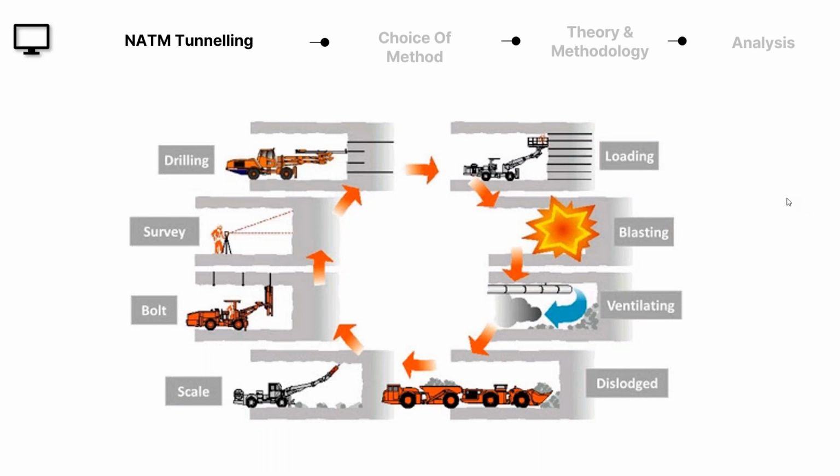The entire chain of process starts with a survey, where we have to drill and what kind of material is present. Post survey, the holes are marked. Then we go to the drilling phase. Normally for tunnels, you will either use a Simba or a Jumbo from Sandvik for drilling. Now these machines are coming with laser guided precision, so drill hole deviations are quite low currently.